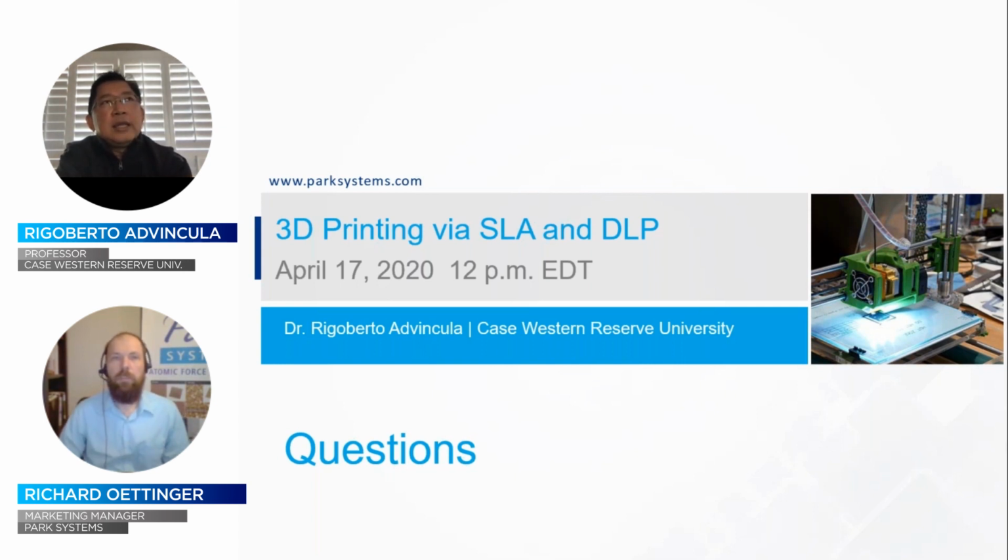So yes, the nanofiller material, and we have worked with a number of them, including graphene, nanoclay, silica nanoparticles. So one is you need to know the nanofiller materials you have. You can confirm that by AFM or TEM even. So the dimension of 100 nanometers to a micron is no problem. A lot of this SLA printing, DLP has a layer thickness anywhere from 10 to 150 microns. So the distribution of the nanofillers at that range on these layers is no problem.